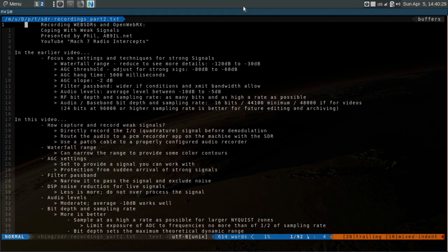Default AGC settings are fine. You certainly want the AGC to remain engaged, and you want the signal to be at a moderate level. Let me remind you once more, the AGC should stay engaged when you're recording weak signals. That's a lesson from experience.